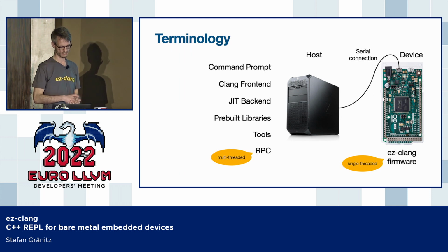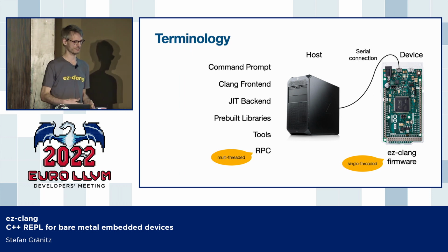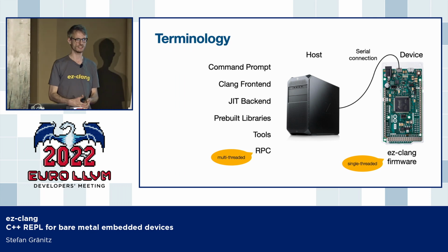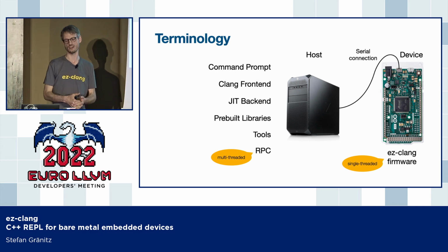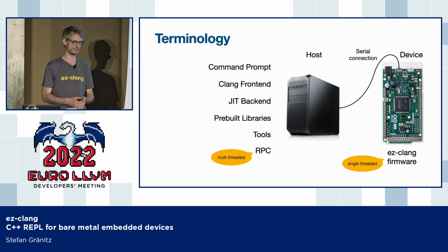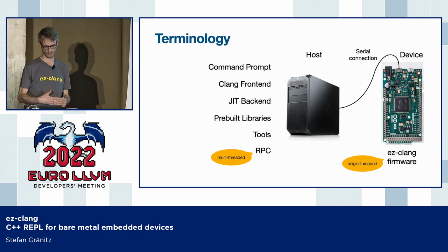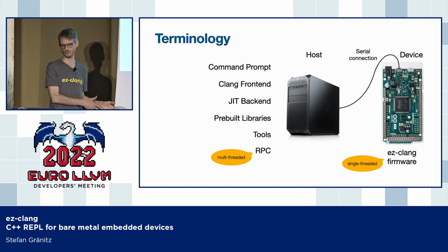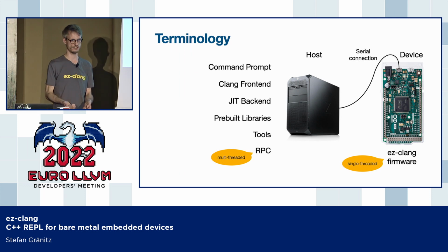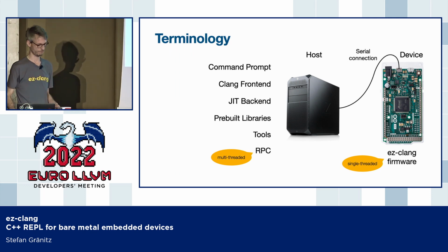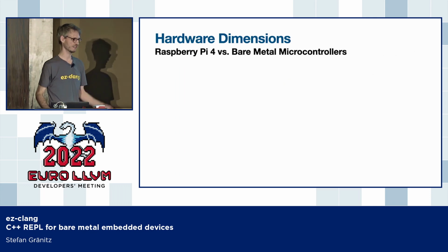The RPC layer is interesting because it allows us to talk to the device, and it's single-threaded on the device, of course. So all traffic is synchronous, and this is very important because the UART component on the embedded device can be operated without interrupts. So that makes the implementation of the firmware a lot easier, and that's basically the whole philosophy behind the project. We want to do all we can on the host and as little as necessary on the device, so the device can be very simple and slow, because simple and slow usually also means cheap, and that's usually an important property.